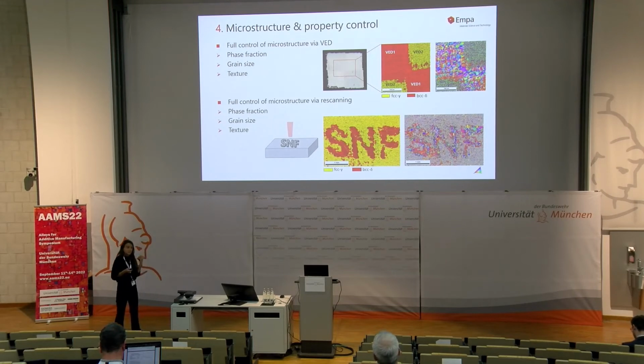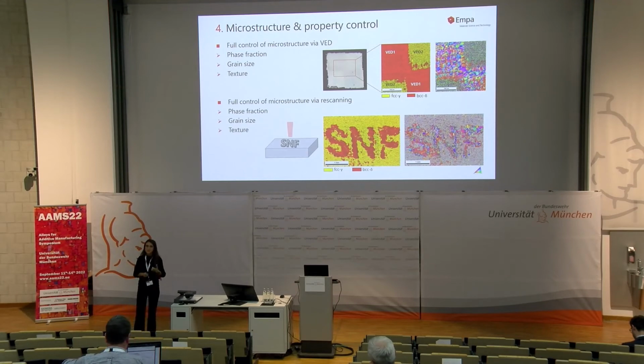So the nice thing here is really to see that we have full control of the microstructure. So with these laser parameters, we can really integrate in a single sample completely different grain size, completely different phases, and also completely different texture.